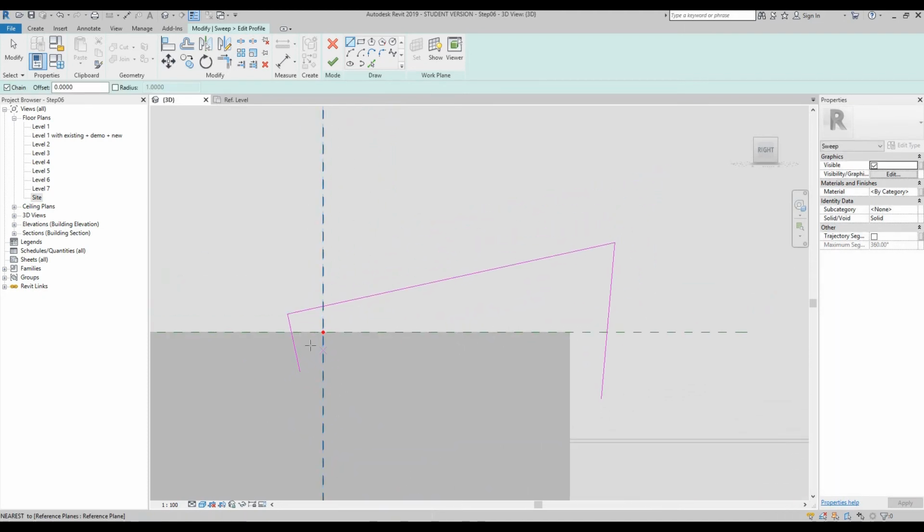But obviously it has to have some thickness. So what we're going to do is offset these 3 lines by approximately 2 mil. To do that we go straight up to our modify sweep tab, and now we're going to choose the pick line tool. But before we start picking any lines we need to change it to 2 mil. So that will be 0.002.